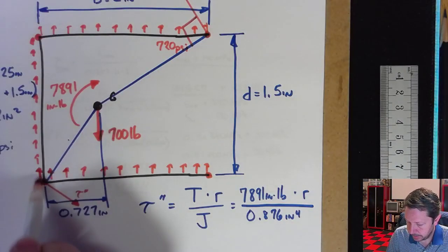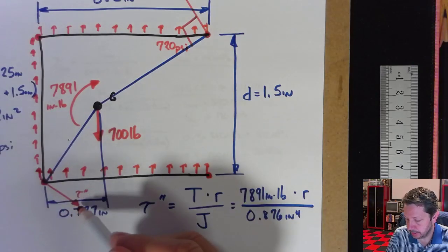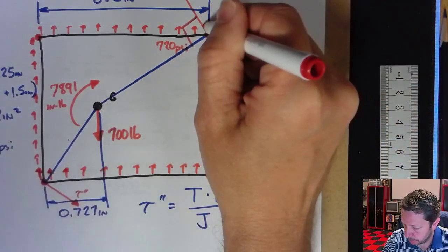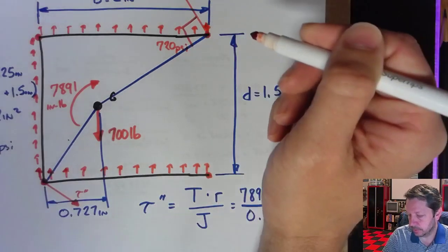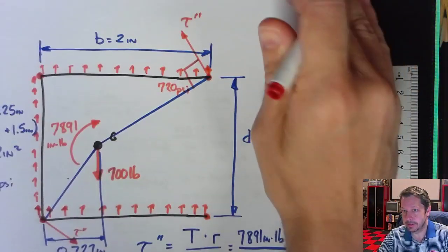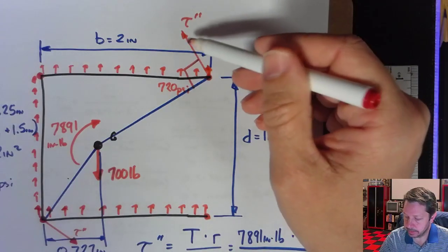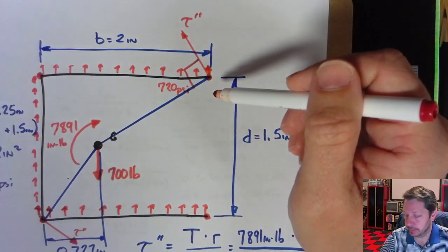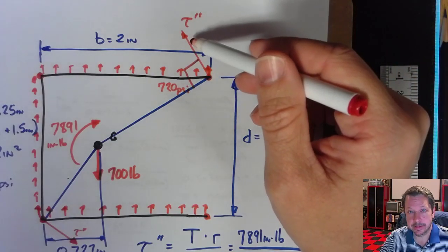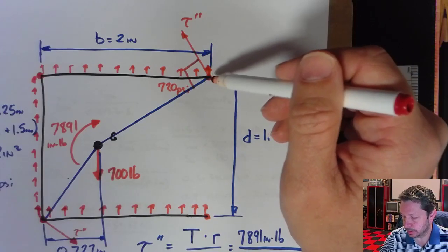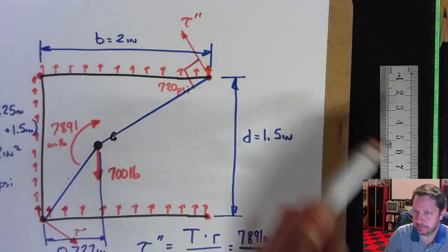And here I've got a positive Y on my primary shear and a negative Y on the secondary shear. So they're going to subtract each other. Here I've got a positive Y on my primary, a positive Y on the secondary. So they're adding, and then I've got a negative X, but I have no X at all on the primary one. So again, that is going to add together because there's nothing else to oppose it. I don't have any primary shear going out that way.